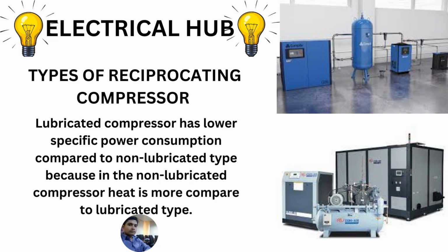And secondly, the lubricated compressor has lower specific power consumption compared to the non-lubricated type because the non-lubricated compressors produce more heat, which is the main source of waste of energy in the compressor.